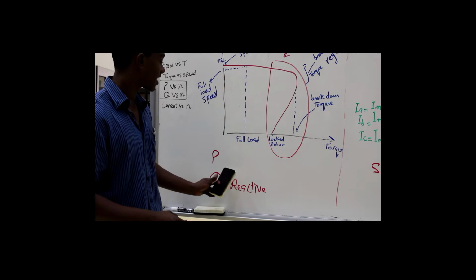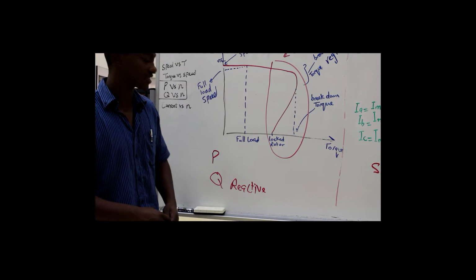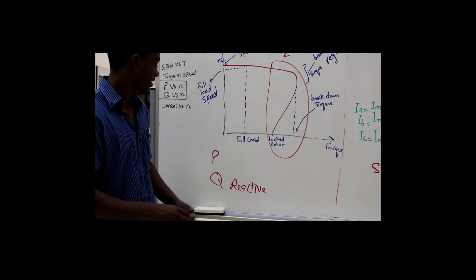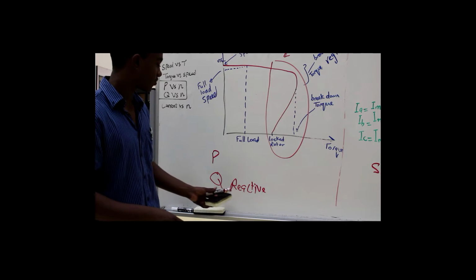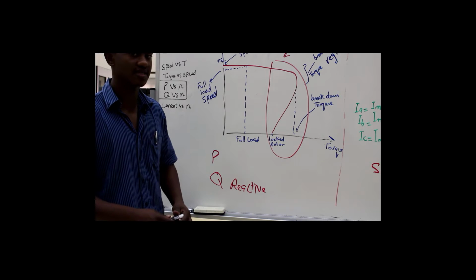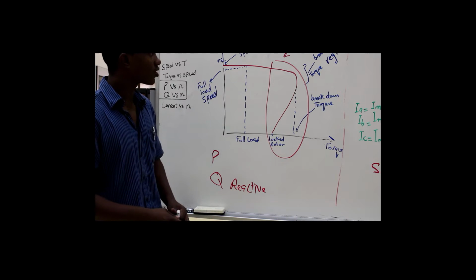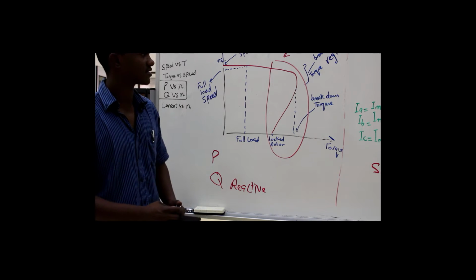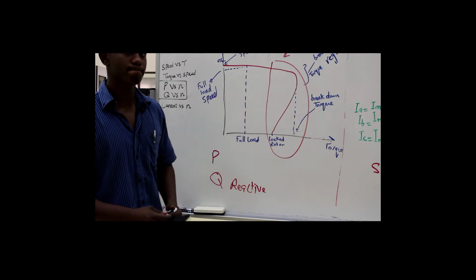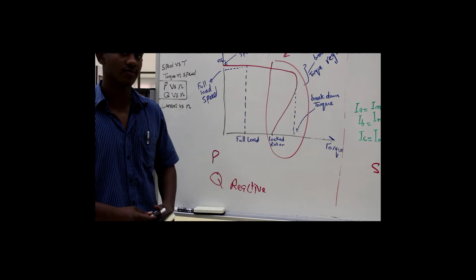When the motor has no load, the reactive power clearly exceeds the active power, because the motor always needs reactive power, but when there is no load, it only needs a little bit of active power. We're also going to see the characteristics of current versus the speed n, and we're going to see that on the computer part when we get the results, and we'll see the graph. Let's move on.